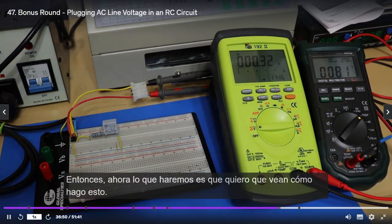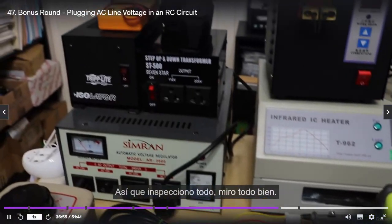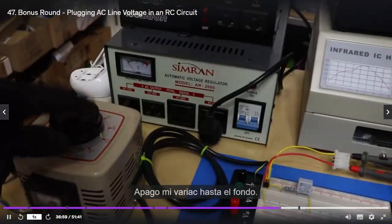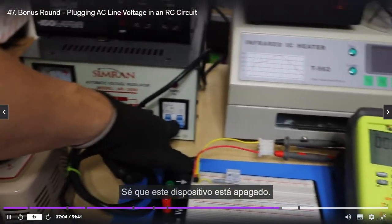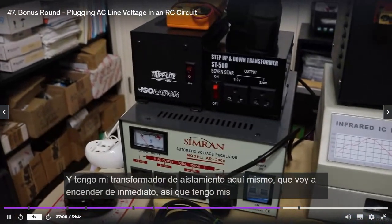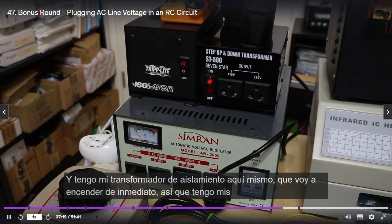Now I want you to see how I do this. I inspect everything, I look at everything. I turn my Variac all the way down. It's on 0, I know that. This device is off, I know that. And I've got my isolation transformer right here, which I'm going to flip on. I've got my goggles, I'm good to go.